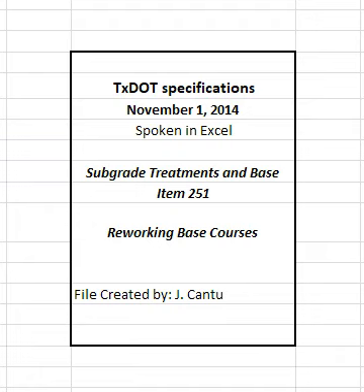Begin rolling longitudinally at the sides and proceed toward the center, overlapping on successive trips by at least 1/2 the width of the roller unit. On super elevated curves, begin rolling at the low side and progress toward the high side. Offset alternate trips of the roller. Operate rollers at a speed between 2 and 6 miles per hour, as directed.